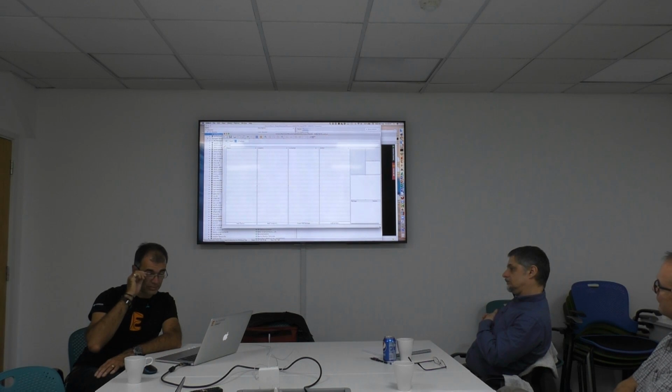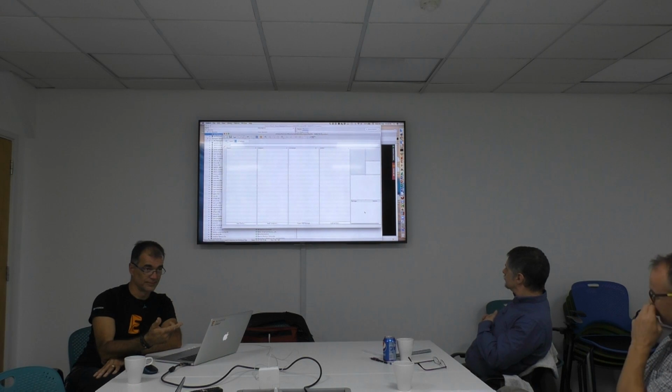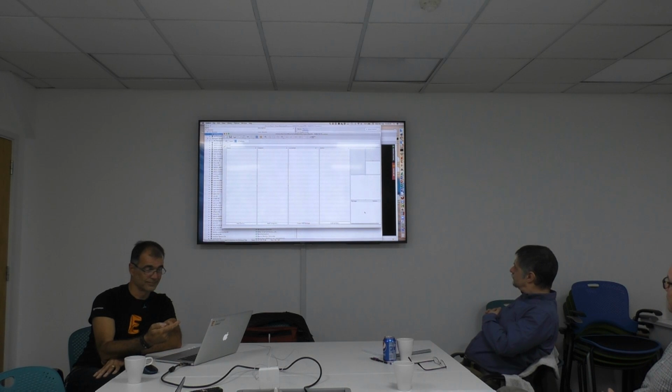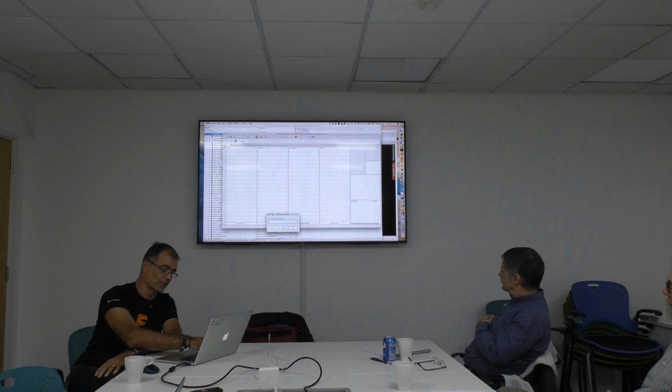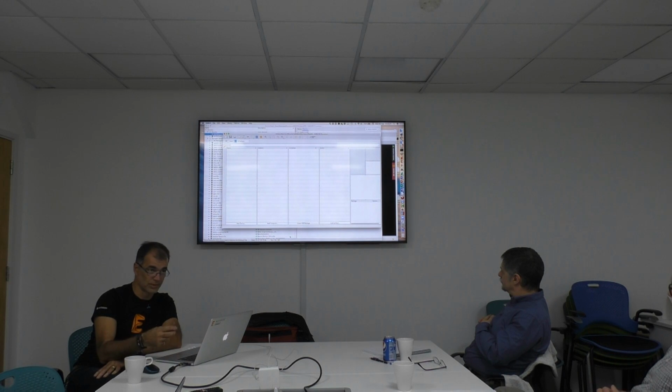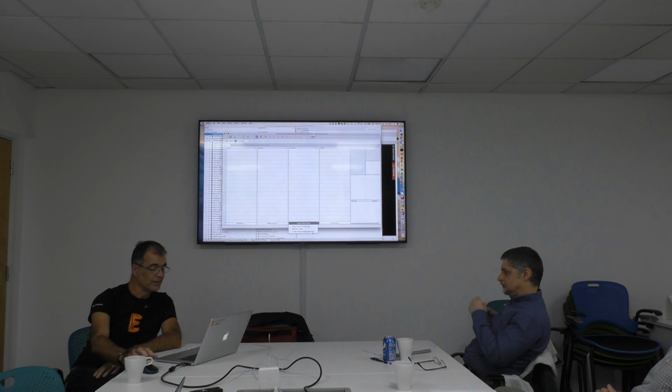If I know what I want to do, here it's not obvious what to do, because I would like to create a footprint now. Where would you click to? I can say add footprint. But that's not what I want to do. I want to use the package generator. I have to go this way there and say create with package. The interface could be better. But okay, I simply show you.